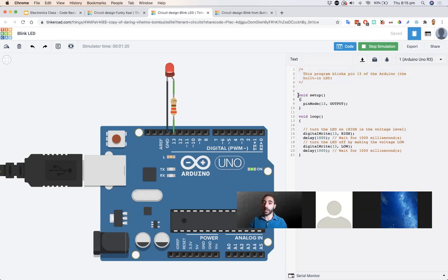In Arduino, we have two main things that always happen. So we've got a setup and we've got a loop. The setup always comes first and is always run once. And we use this to set things, set our environment a certain way. So as we read down, what happens is we hit this setup first and it runs this command.